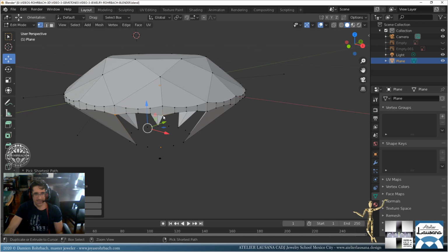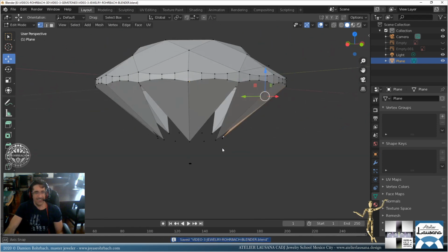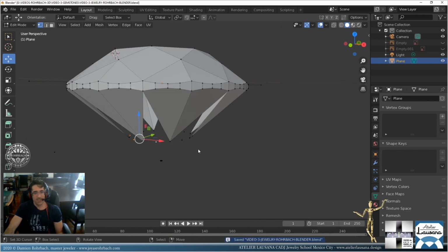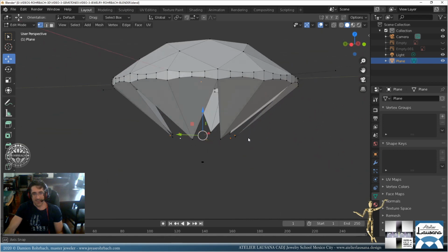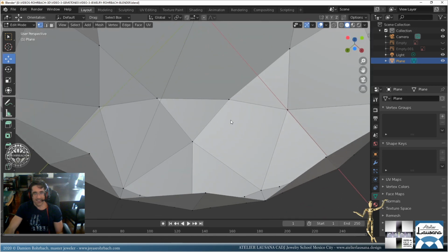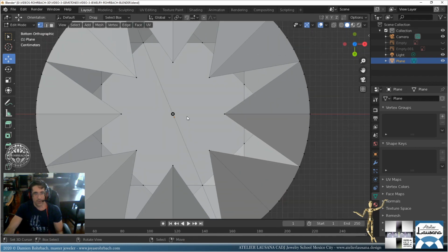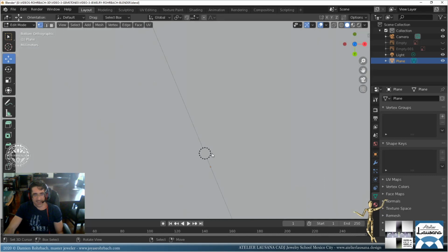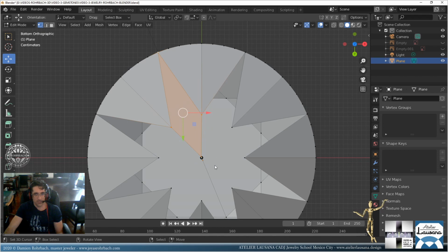Okay, this is very nice. Here. Okay, this is great. Are we good? Okay, that's perfect. Now I can remove. Well, you can remove them before, but I'm showing you how to do that step by step. Okay, let's remove these vertices. Now we need to select. This one is not so easy, so let's do a control 7 to have the down view, because we need to select this vertex, this one, and that one, F.